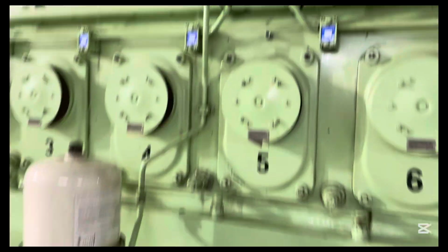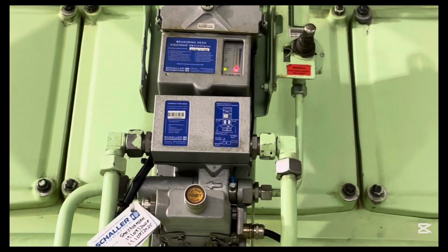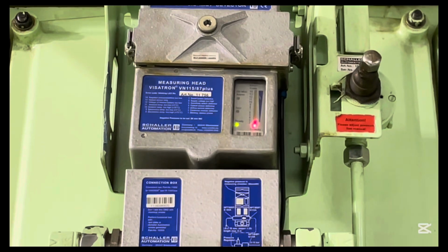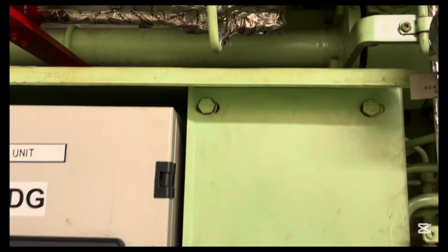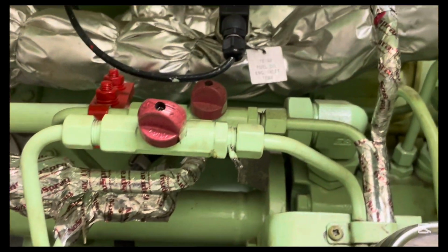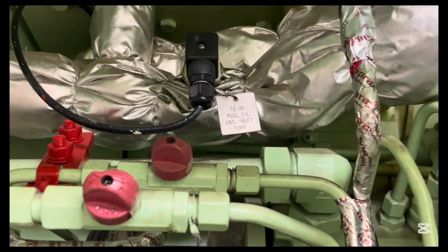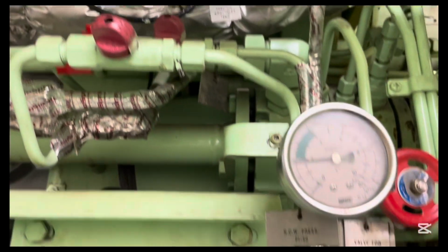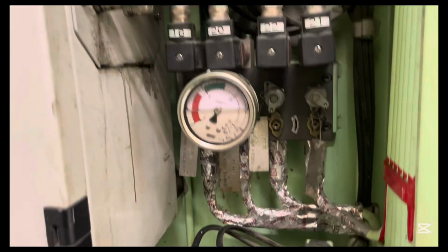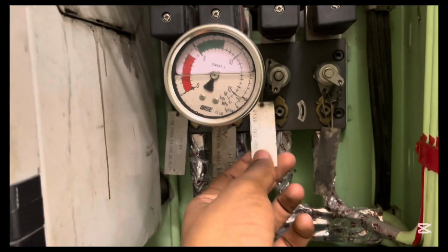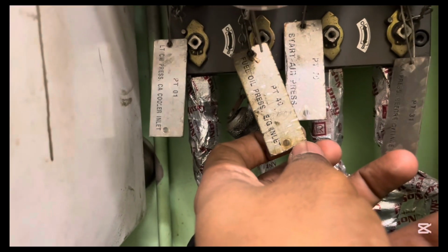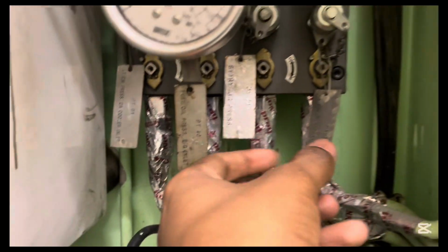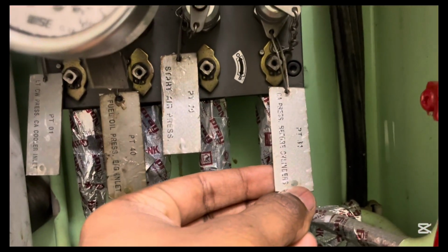All right, now let's get into the alarm and trip section. So this is the oil mist detector alarm. Initially it gives the alarm, then it will trip the engine. The second one which we see here is the fuel oil inlet temperature alarm. That is a temperature transmitter, and OMD is an oil mist detector. And here we see the pressure transmitters, which communicate with the control module using the analog signal, which I told you,